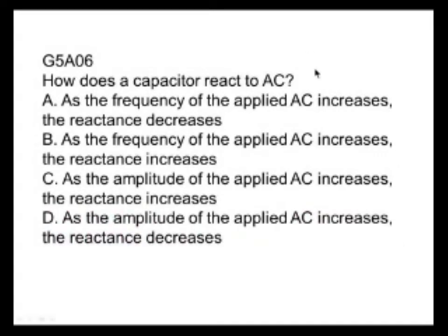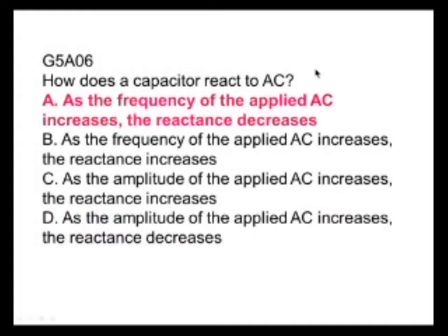How does a capacitor react? Just the opposite way. As the frequency of the applied AC increases, the reactance decreases. So AC flows more easily through a capacitor if its frequency is higher.